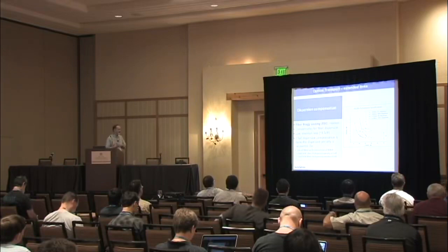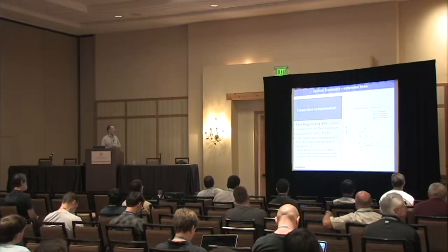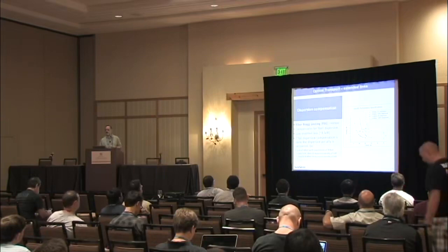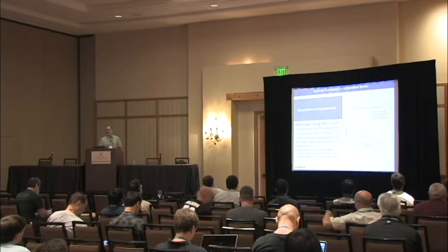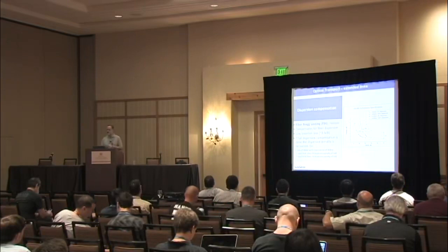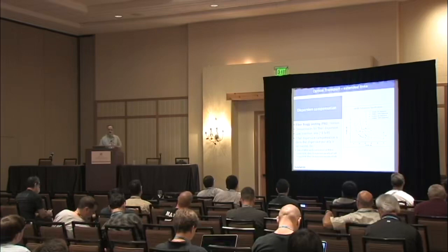So I have an example here. You have a link of 90 kilometers with a transceiver of 80 kilometers, and we are going to talk in kilometers, even if we should talk in ps per nanometer. If you had a DCM of 10 kilometers, you're still going to pay the 3 dB penalty that we mentioned before. If you had a DCM for 90 kilometers, you recover those. Your dispersion penalty is going to be 0. So if you need those 3 dB, that's a good way to recover. And again, that's good for 10 and 40 gig; 100 gig is a different story. 100 gig coherent optics like dispersion.